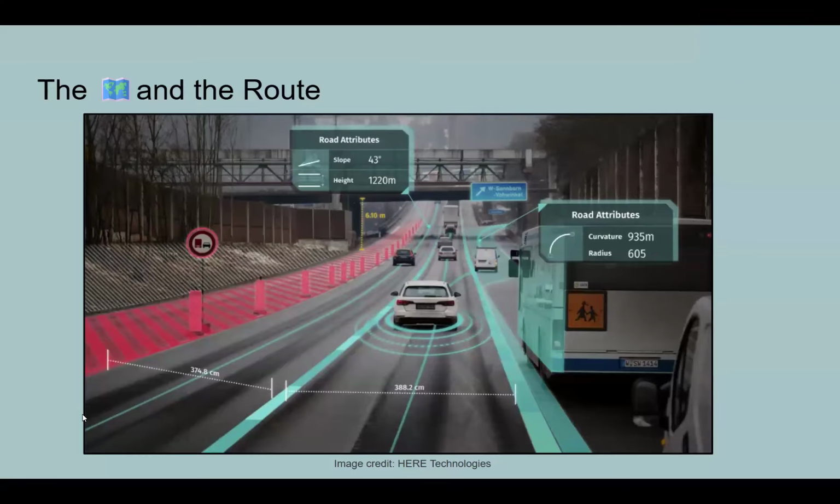Okay. Also, there is one thing that I would want to add from my end. Maybe that might give you more clarity about this topic. When Aditya is talking about planning, it's split into three segments, and it's hierarchical. And the rate at which it iterates is different. There is a global planning or route planning that Aditya has been talking about, in terms of Dijkstra or A star. Then comes behavior planning, and then comes local planning.